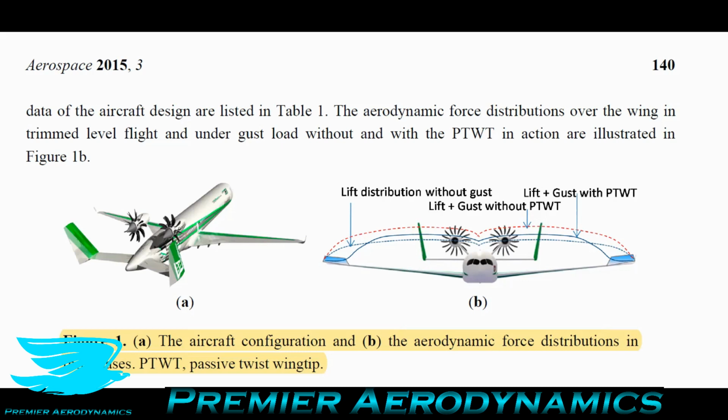So what this means is that the critical Mach number is not that high. It's not 1. The reason why is because over the airfoil, the flow accelerates. And so even though the free stream may only be Mach 0.85, the local velocity over the airfoil could reach 1. It could be sonic. So by sweeping the wing, you make the effective airfoil profile thinner, and that increases the critical Mach number, which means you can fly faster without reaching the sonic barrier and without increasing the wave drag.